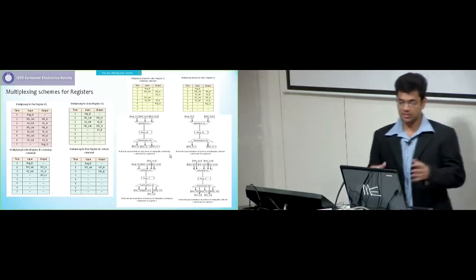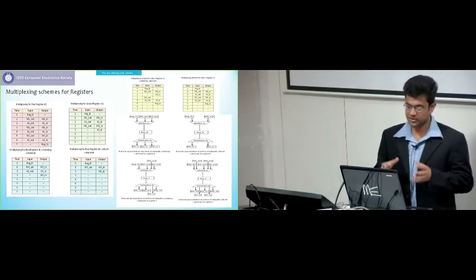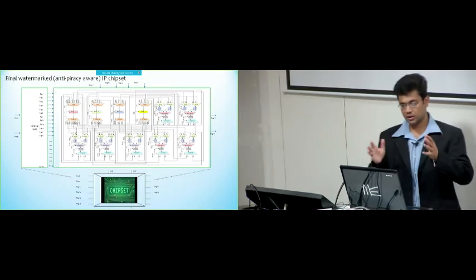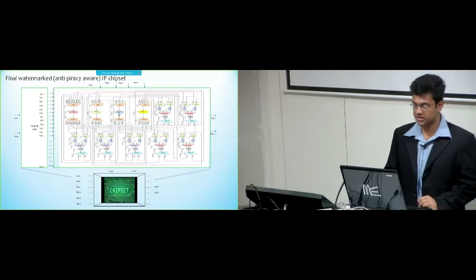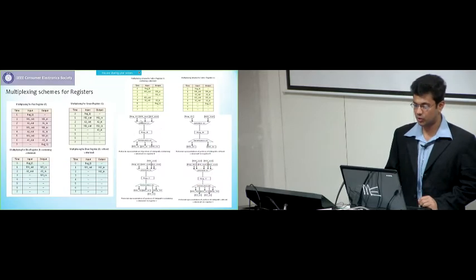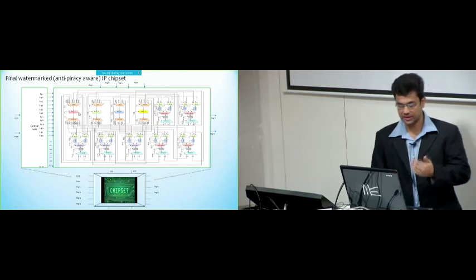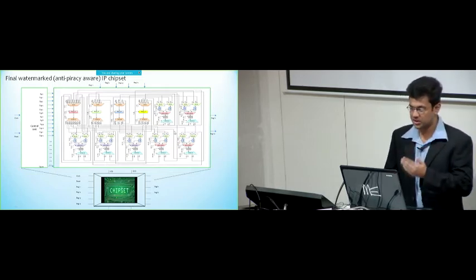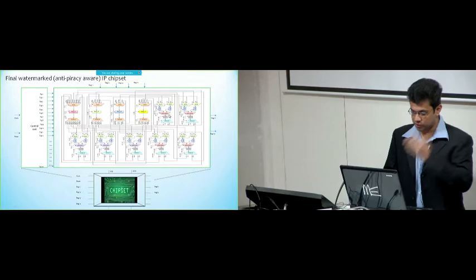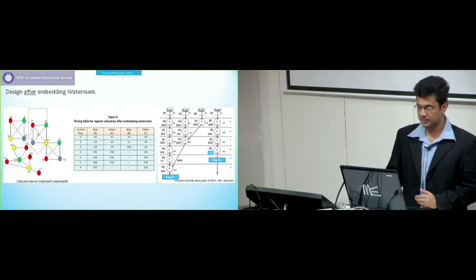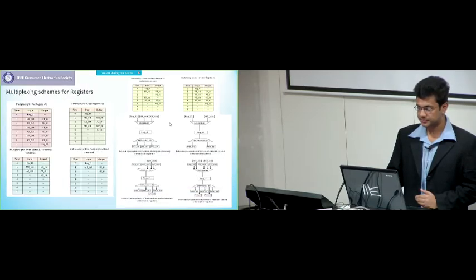Now once we have the multiplexer structure and information of the circuit available to us, we can easily put this into a final corresponding data path, where you could see the blue and yellow registers are exact replicas of what we have extracted or derived here. The remaining ones just indicate, by following the same process, how we can get the connectivity information of register RG and resources M1, M2, M3, M4 followed by A1, A2, A3, which are the resource information of the scheduling graph.